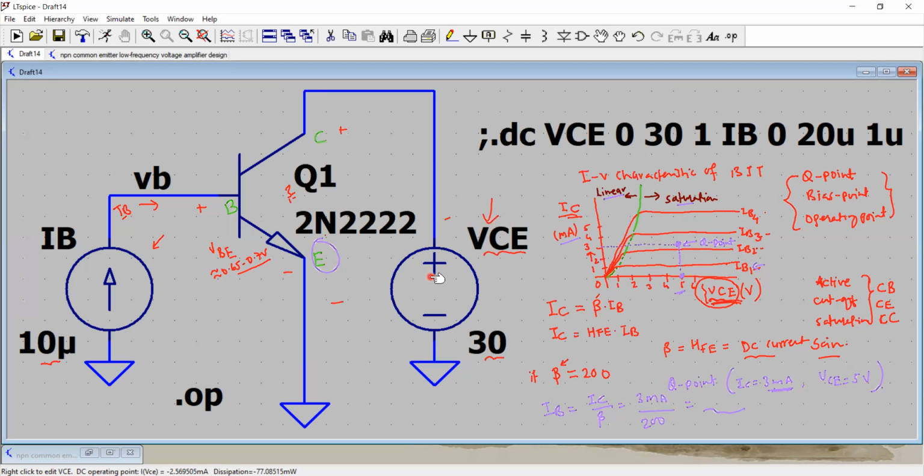If you design an amplifier or any other circuit, you often need to use a transistor with proper DC biasing. For that, you need to set an operating point for given values of the output current and the voltage across the transistor.